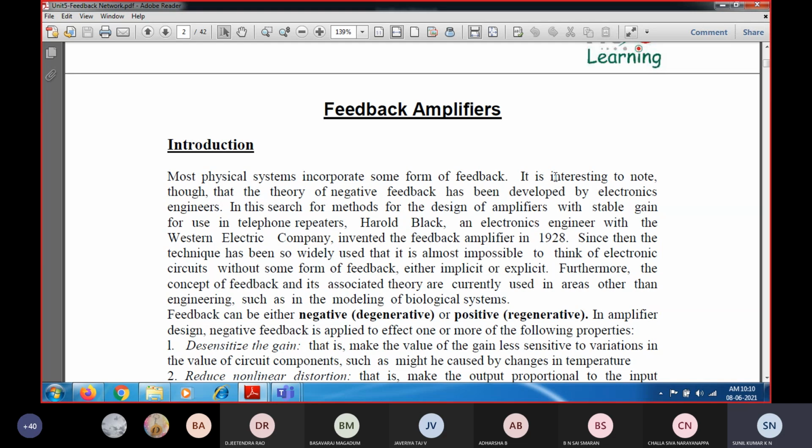And after finding all this, we started with the applications related to amplifiers. That is the oscillator circuit. In the oscillator circuits, for a given common source or common emitter amplifier, we have seen three basic categories. One is the RC phase shift oscillator, which has a main amplifier section as well as a feedback network connected in parallel with respect to the amplifier. Part of the output will be given as the input to the feedback network, and the output of the feedback network is again fed back to the input.